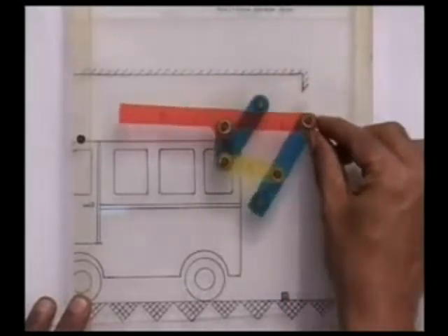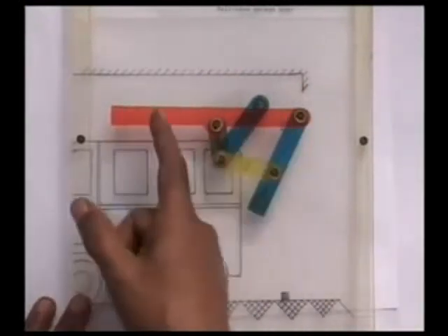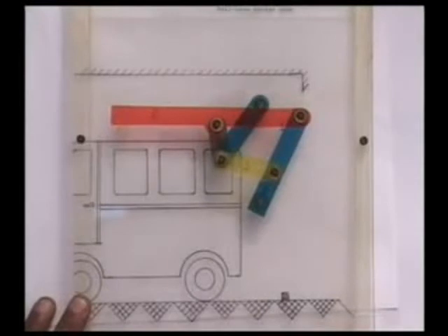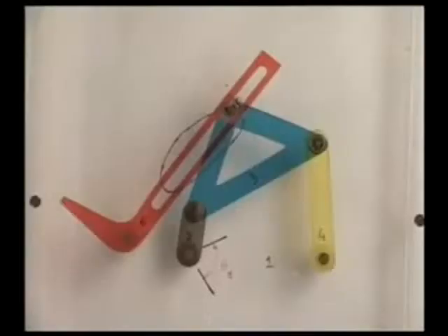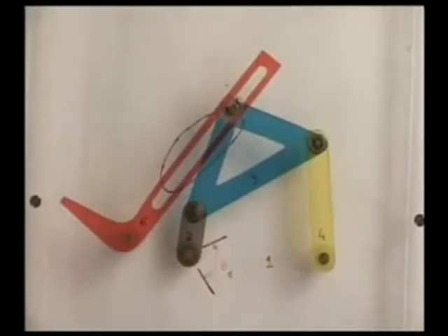And such a movement is not possible by using a simple 4-link mechanism with the door board as the coupler. So we go for this 6-link mechanism. And now we shall give the details of the design of this 6-link mechanism and determine all the kinematic dimensions by applying the multi-stage synthesis procedure that we model. Let us look at this model of this 6-link dual mechanism.